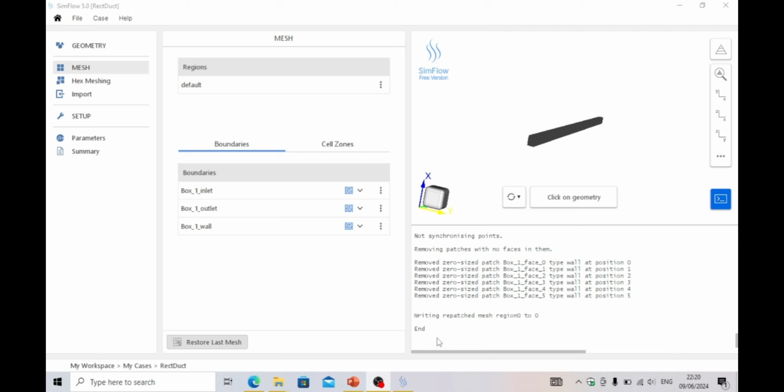So the mesh is generated. So you will get this. If the number of nodes generated are more than 200k, then a message will pop up, so that you have to reduce the number of divisions in the earlier window and remesh. So here luckily it is not the case, so the mesh is generated.